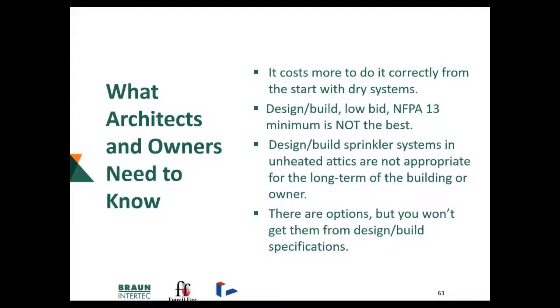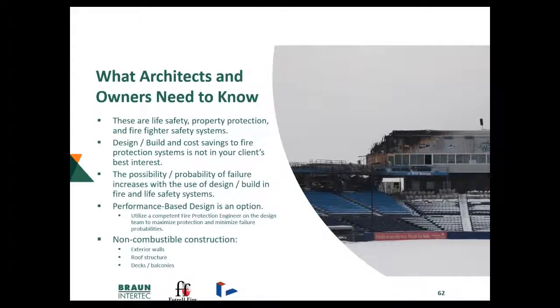Design build sprinkler systems in unheated attics are not appropriate for the long term of the building. It's just not the best. You can give some minimum standards which you need to provide, but just design build would not do it. There are options, but you won't get them from the typical stamped design build specifications that we see. So these systems that we're talking about, we need some sort of fire protection. They are life safety, property protection, and we often overlook firefighter safety systems.